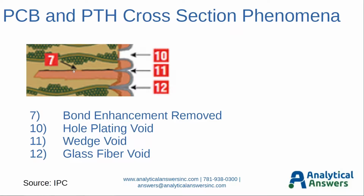Number 7 right here is a bond enhancement removed. So on the smooth side of the inner layer foil here, they've added a black oxide preparation step to create a greater surface area and bonding strength to the inner layer laminate material here. So in this particular case, it's missing, and if we were to look at this in the horizontal orientation, this would be called pink ring. And basically, this would be a black region here, this would be pink, and again, another common name for this is pink ring.